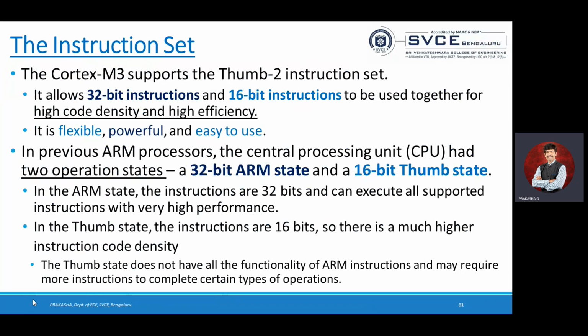It can take care of 16-bit data also, Tejas, and it can also take care of 32-bit instruction also. A Thumb instruction was taking care of only 16-bit, but Thumb-2 can go for 16-bit, it can go for 32-bit. There is no difference. ARM instruction is always 32-bit. ARM instruction will always take care of the 32-bit instruction. But sometimes I need to deal with 16-bit data. Sometimes I need to deal with the 32